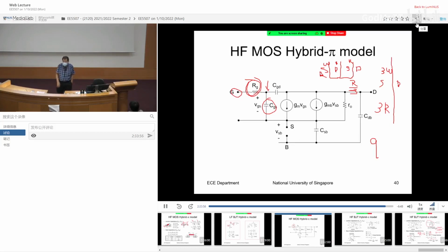You get the point? That's why for RF, high frequency, you always use short width, multiple fingers. You don't try to use long width. So how short is short? It depends on the frequency. Some people say anything below 10 micron. So if you're more than 10 micron, chop it into different fingers. But we worked with one industry partner. The engineers shared with us that if you are talking about the gigahertz range, maybe 5 or 10 gigahertz, try to keep the finger width less than 2 micron. The shorter, the better.